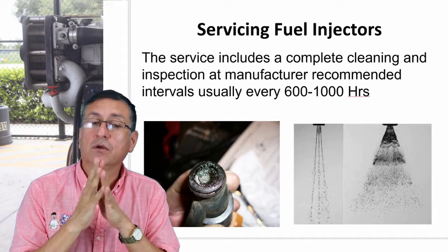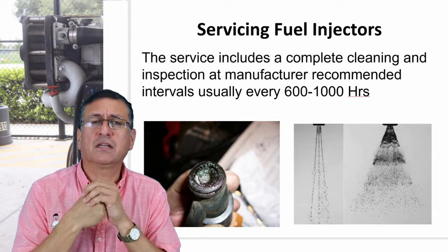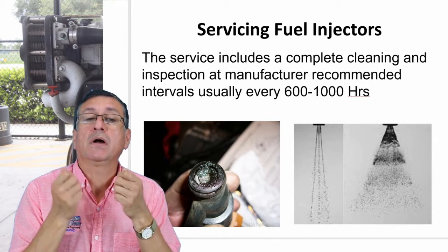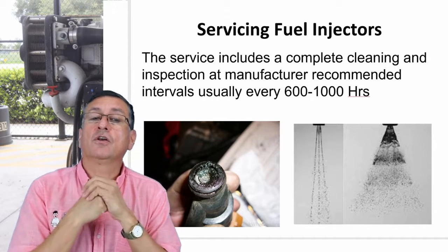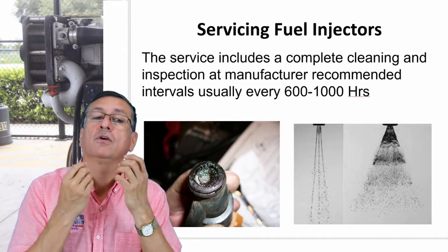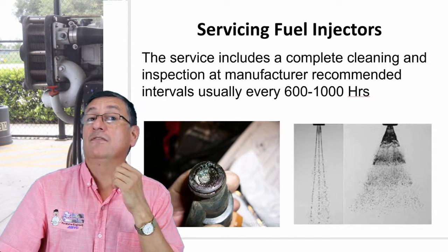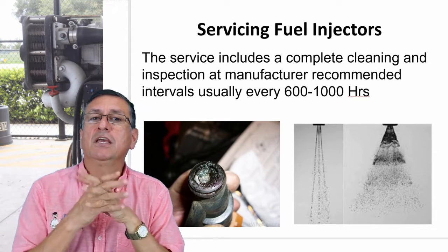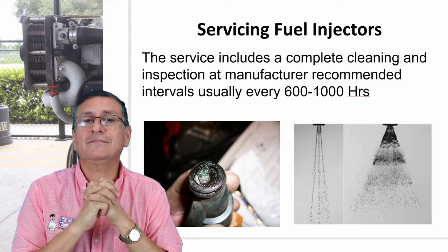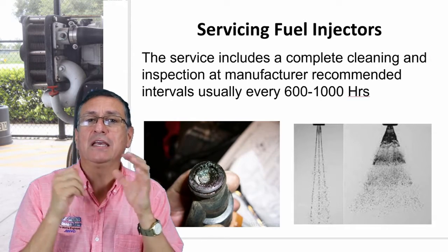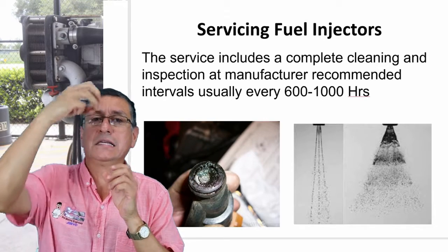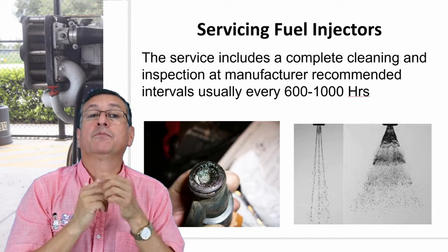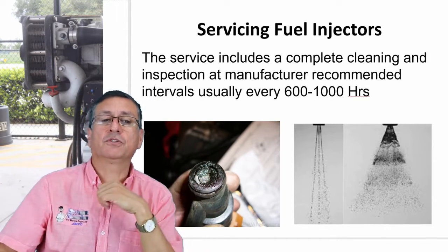I recommend doing the service every 1000 hours, between 600 and 1000 hours, on the injector. Verify periodically with a magnifier the condition of the nozzle. Verify if the nozzle is in good condition, if the nozzle is eroded, or if the nozzle is clogged with oil. If the nozzle of the injector is clogged with oil, probably it's because you have blue smoke. If you have blue smoke, remember, normally it's a problem on the valves, on the seal on the valve, or normally the guide between the valve and the valve guide has too much play and the oil penetrates into the combustion chamber.